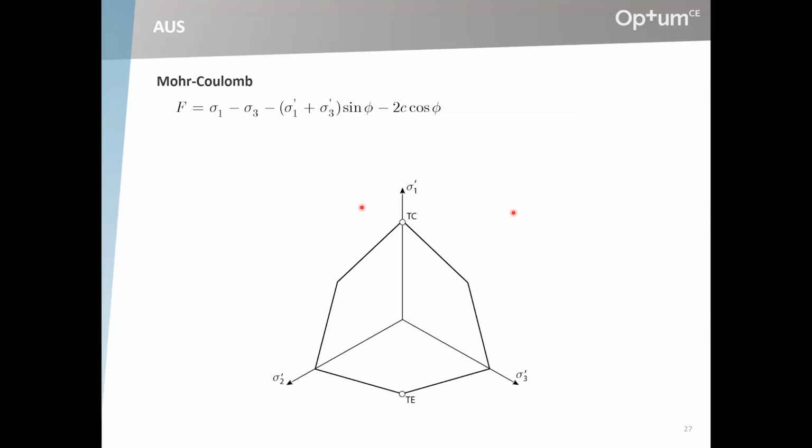So suppose that the effective stress behavior is governed by Mohr Coulomb, and suppose that we set up a very simple linear elastic perfectly plastic Mohr Coulomb model and then did an undrained, so a coupled pore pressure deformation analysis type test. What we would find is that the mean effective stress does not change during the test, whether it's triaxial compression or extension, doesn't matter.